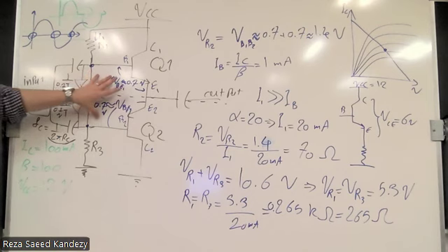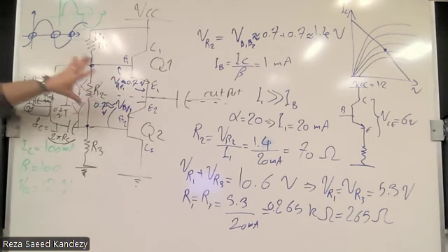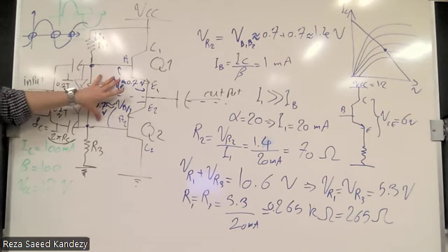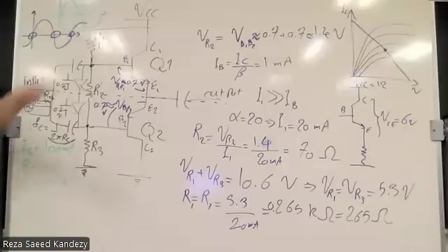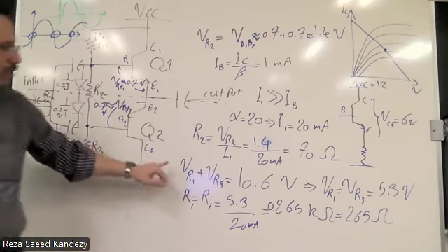So still we had 1.4 here. Now with the diodes, we make sure that we always have 1.4 here. So the rest of the circuit is going to be the same. The only thing that you change is that you don't need the R2, so forget about that. It becomes R1 plus R3, 10.6, and then you just go. Yes, you start from here.